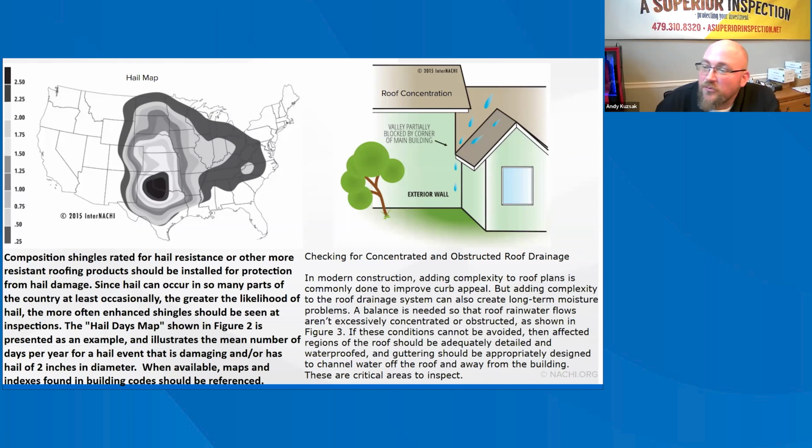Minimum roof penetrations. Roof penetrations increase the likelihood of water leaks due to failed gaskets, sealants, and flashing. The number of roof penetrations may be reduced by a variety of technologies and strategies, including AAVs, which are air admittance valves, to reduce or eliminate plumbing vent stack penetrations, consolidation of vent stacks below the roof, like sidewall penetrations, exhaust vent caps routed through walls instead of through the roof, high efficiency combustion appliances, which can be sidewall vented, and electrically powered HVAC equipment and hot water heaters.